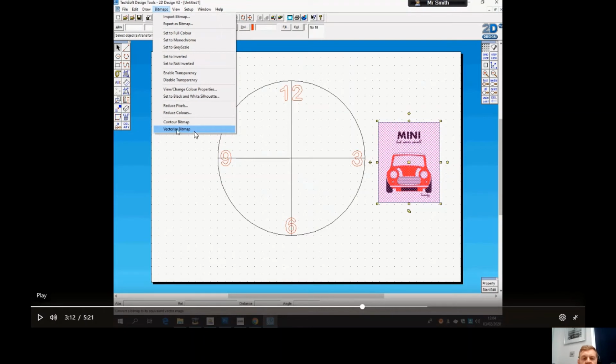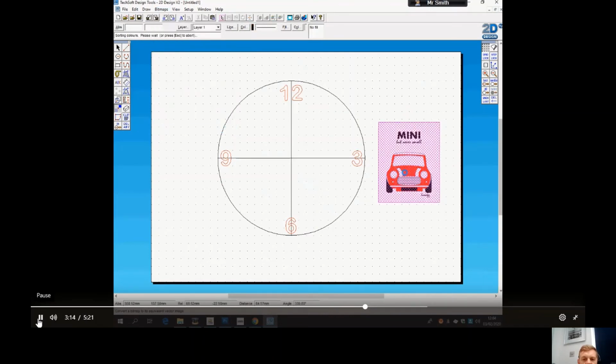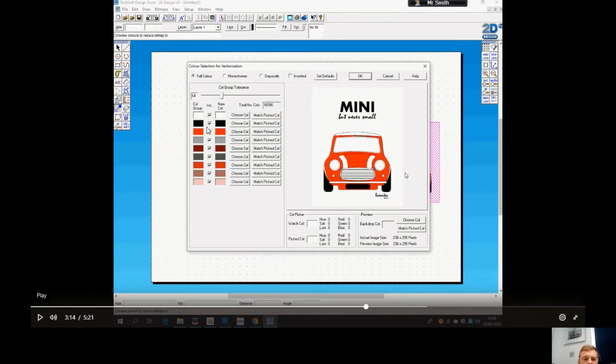Okay, and basically what the laser cutter does is it reads the coordinates. So it will say the first place I'm going to engrave or cut is 2 down, 2 across. The next place is 3 down, 3 across. But the laser cutter doesn't understand bitmaps; it can't figure them out. So you need to always convert the image into a vector image. You can see, you click on the image and it brings up all the colors that the image is made up of.